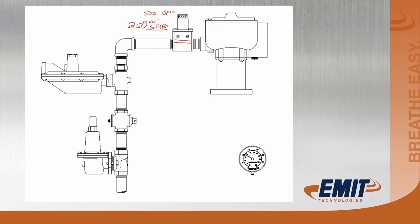Then we're going to go down here and we're going to adjust our fuel pressure. Now, the other thing is the regulator is designed to maintain fuel pressure on fuel that's flowing. So you want to start your engine and idle it; that is the most common way to set your fuel pressure and the most accurate way to set it.